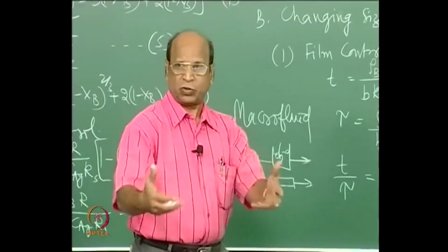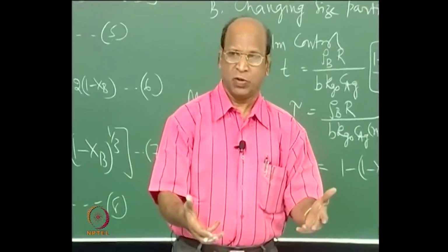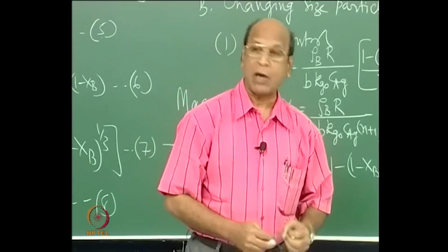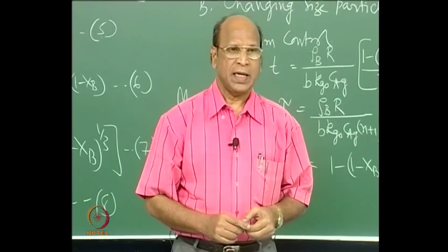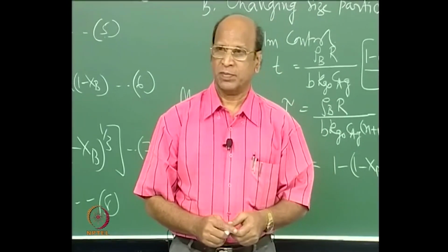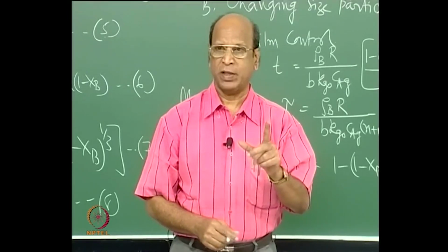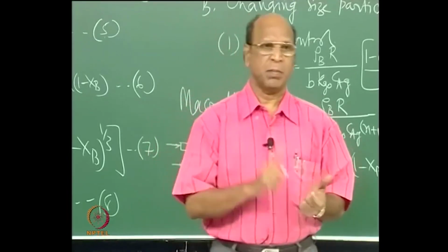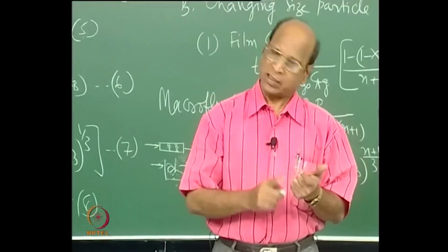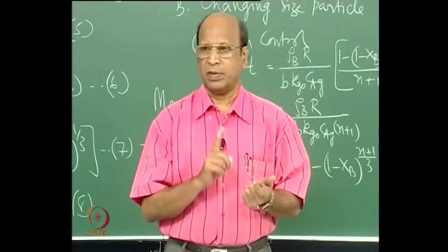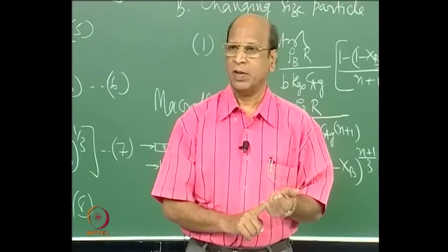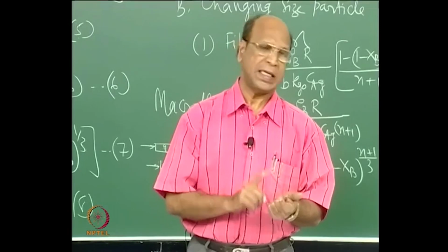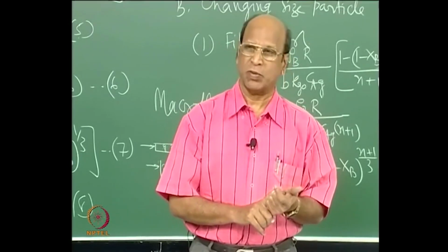And I can also tell you a story, like a story only I am now trying to tell you. Now we can say that if I have macrofluid and a second order reaction, in a mixed flow reactor, remember 3 conditions: mixed flow reactor, second order reaction, macrofluid. And the other case is again a mixed flow reactor, now not macrofluid but microfluid, and second order reaction. Which one will give you more conversion?